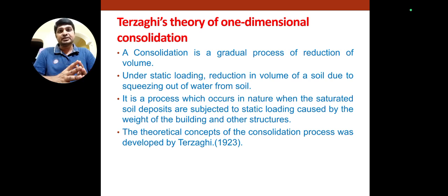With this introduction, I am going to explain Terzaghi's theory of one-dimensional consolidation. Consolidation is the gradual process of reduction of volume. Under static loading, the volume of the soil reduces due to squeezing or expulsion of the water from the soil. It is a process which occurs naturally when saturated soil deposits are subjected to static loading caused by the weight of a building or any other structure.